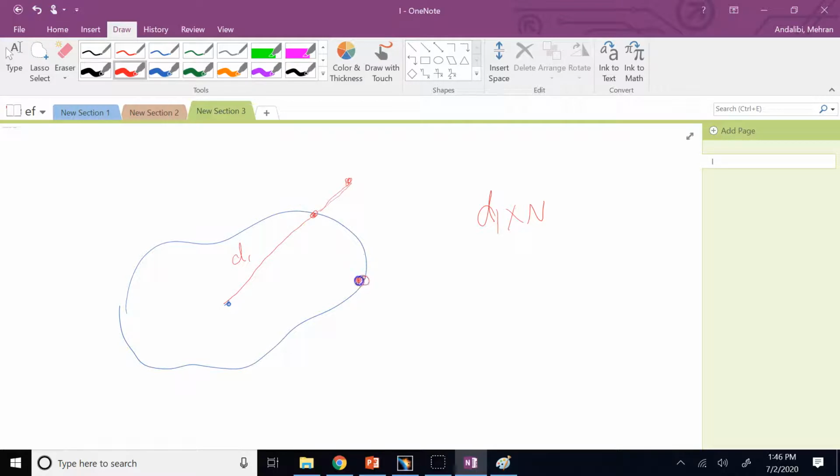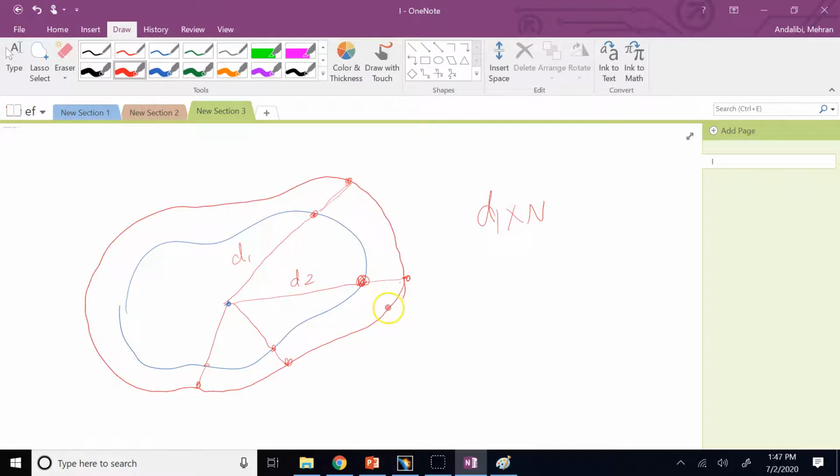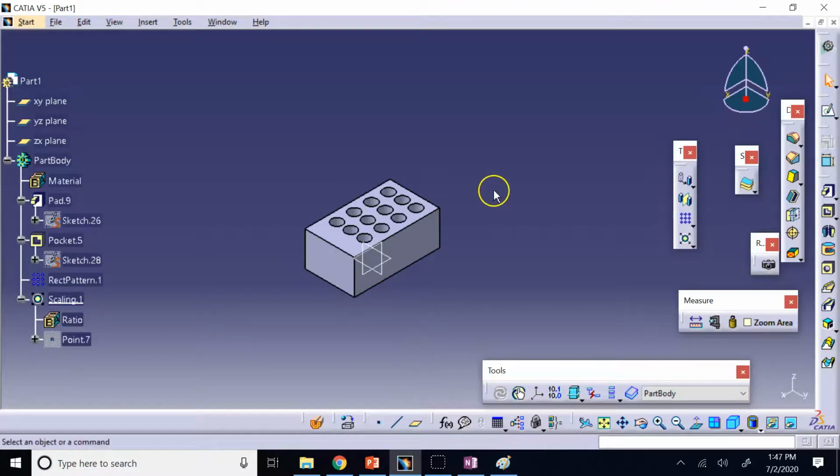Then this point also is connected to the reference point. And then this D2 is multiplied by 1.3, so it comes here along the same line. This point comes here, and then you repeat, right? This point now comes to here. This point comes to here, and so on. And then you connect all of these points together. And you say this object is scaled with respect to that point by a ratio or factor of 1.3 or 0.5 and so on. Okay, so that's the meaning of scaling.